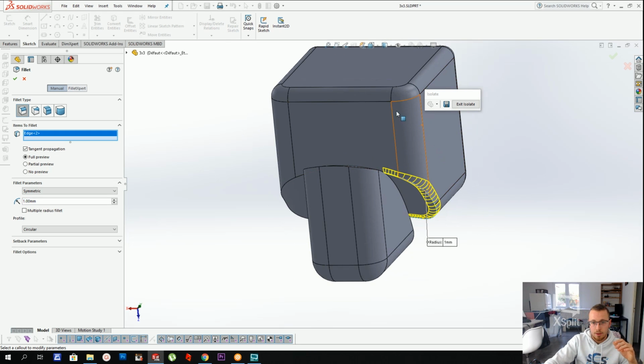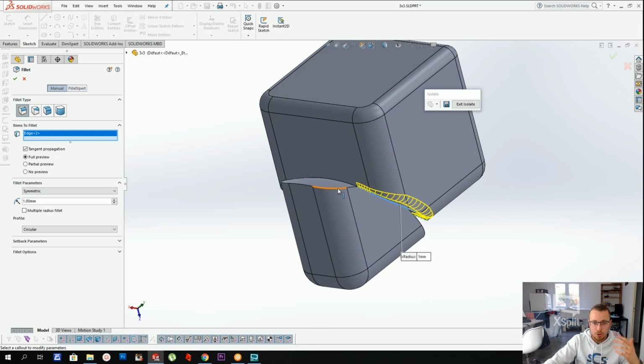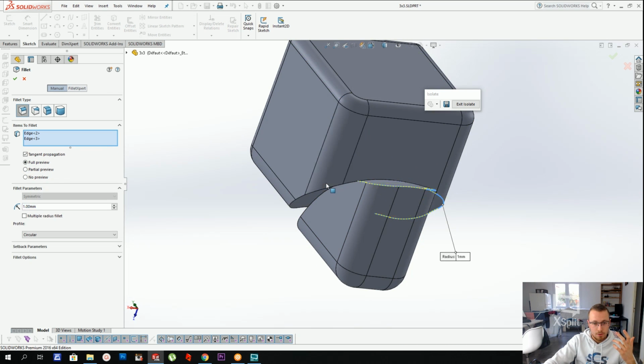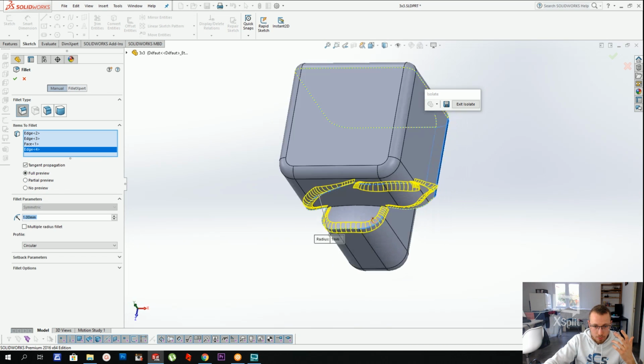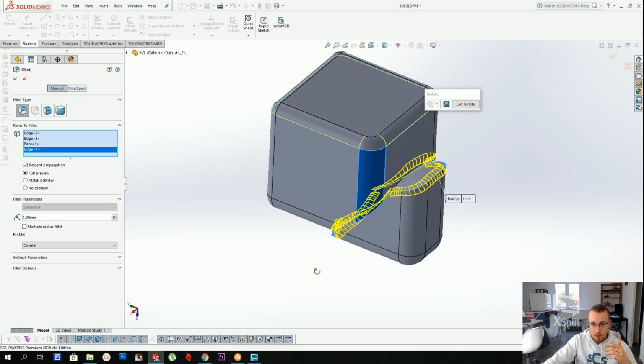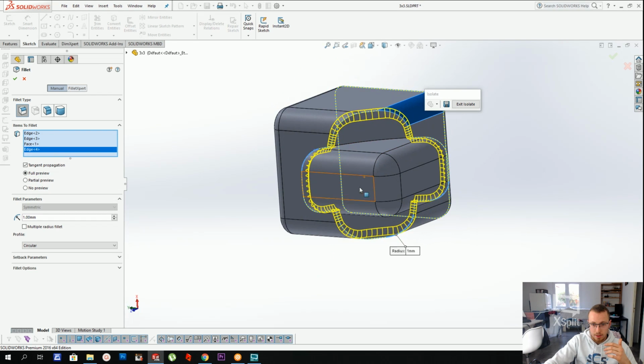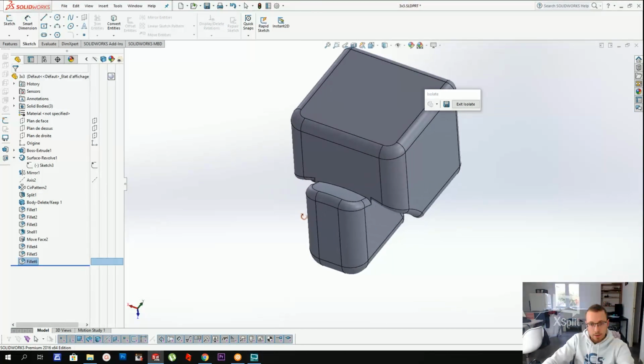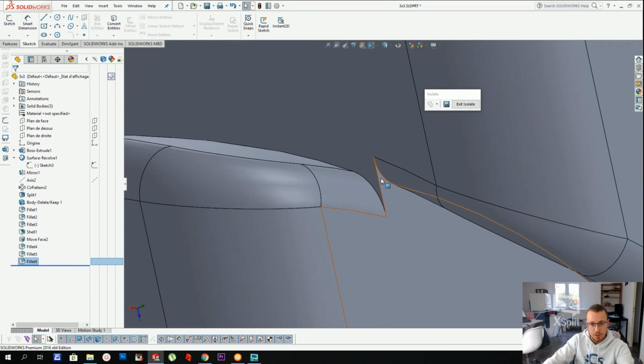So here you've got the outer layer and the mechanism layer. You don't want these to catch together, so you need to add fillets there. So here I'm going to add fillets everywhere. So one here, one on the opposite side, and some on the sides right there. And now, there is only one thing left, these sharp edges right there.